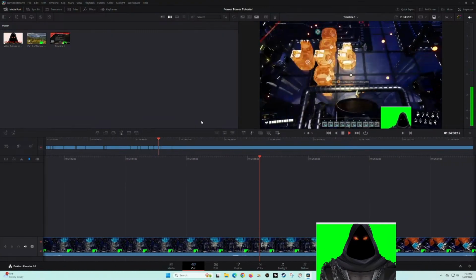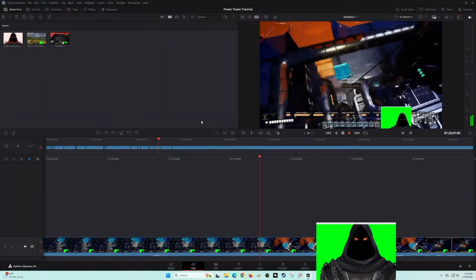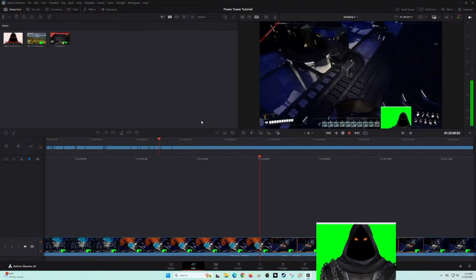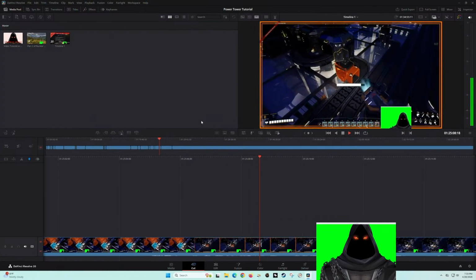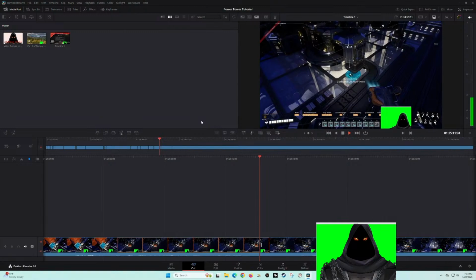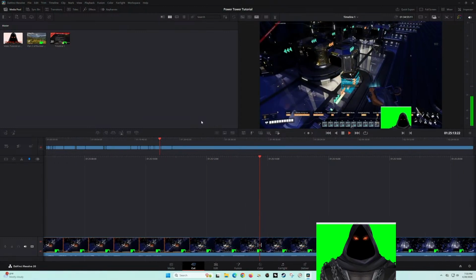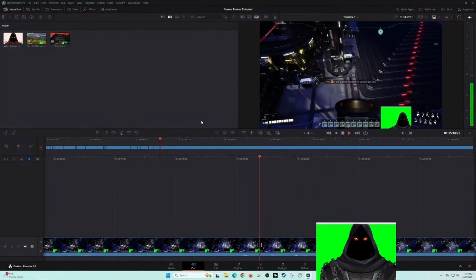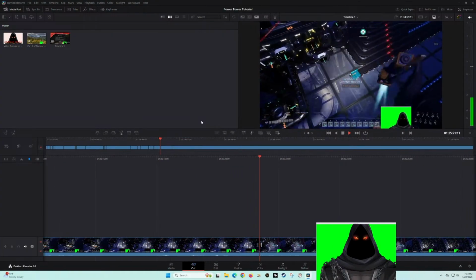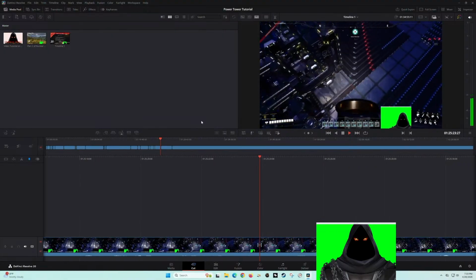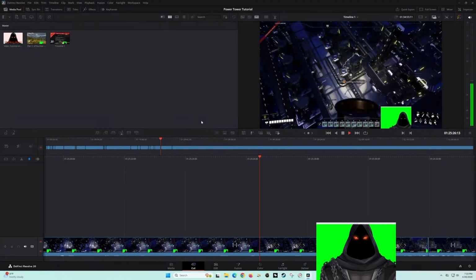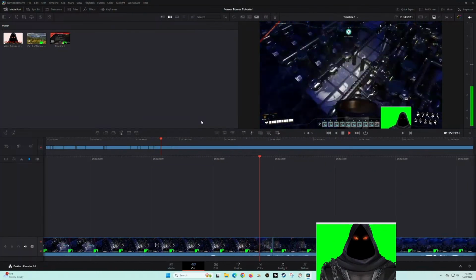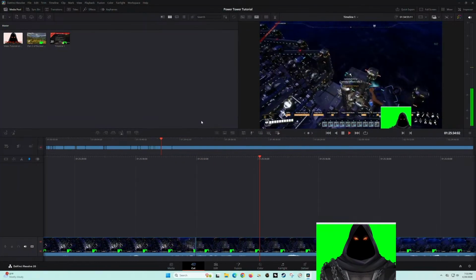Like this. This one is very close, so we're going to have to rotate this elbow here 90 degrees like this. And now they should be connected. And then I'm going to connect this line for the packaged water going up the stack. Okay, so those are connected. Sorry, there's one more thing we have to do.